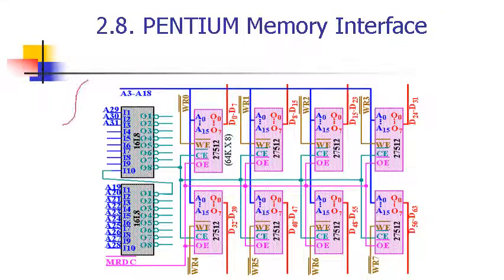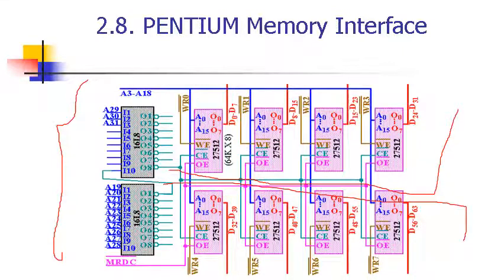Here is the circuitry which shows you how these 8 memory chips, 8 memory banks, are connected to your Pentium processor. We have 4 upper banks and 4 lower banks. And we're using here the PLD, the programmable logic devices 16L8, to enable your banks.